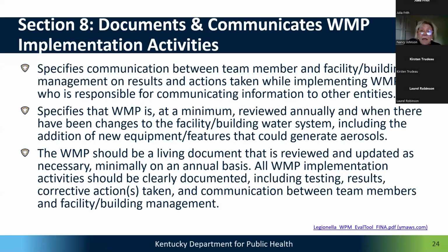It has to be, and when there's been changes to the facility building water system, including the addition of new equipment or features that could generate aerosols. It has to be a living document that's reviewed and updated as necessary, minimally on an annual basis. All of your implementation activities should be documented, including testing results, corrective actions taken, and communication between team members and building facility management.